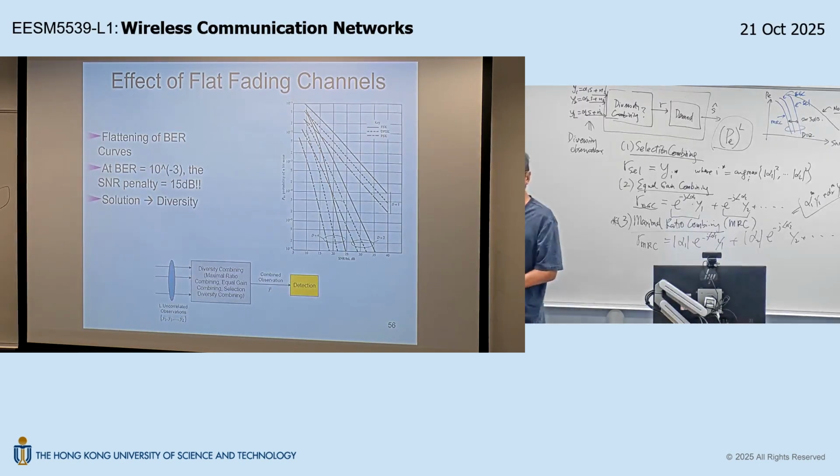Understand? Now, if the switch is in position 2, the same happens because you only have one RF and ADC chain. Then the baseband input to the channel estimator will contain alpha 2 only, right? And then following this channel estimation, you can only get alpha 2 hat. Is that okay? But you need to know alpha 1 hat and alpha 2 hat before you know how to configure the switch. Then what do you do?